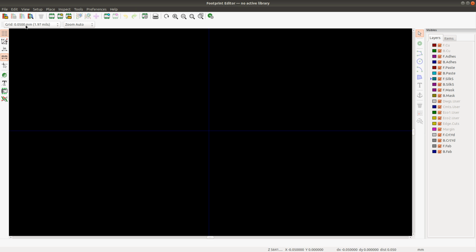That would be very nice. And also something that freezes the footprints, so that if my footprint library gets updated, I don't have to review my components again. And I might actually write some script that will extract all of the footprints from the default libraries and place them into my custom library that goes together with my component library. I think that would be probably a better way to solve this.